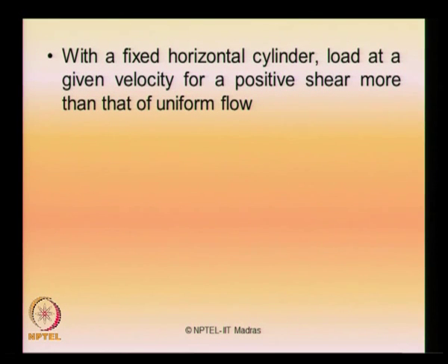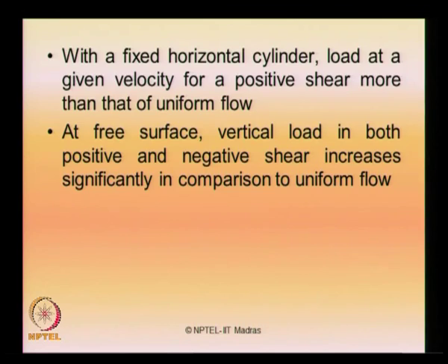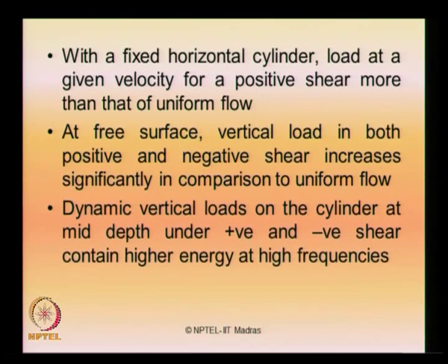For a fixed horizontal cylinder, the load at a given velocity for a positive shear is much more than that of uniform flow. At a free surface, the vertical load in both positive and negative shear increases significantly in comparison to uniform flow. Therefore the dynamic vertical loads on the cylinder at the middle depth under positive and negative shear contain very high energy at very high frequency.